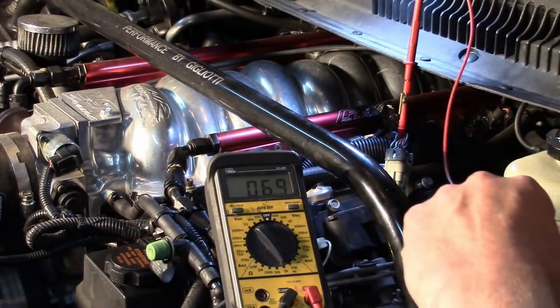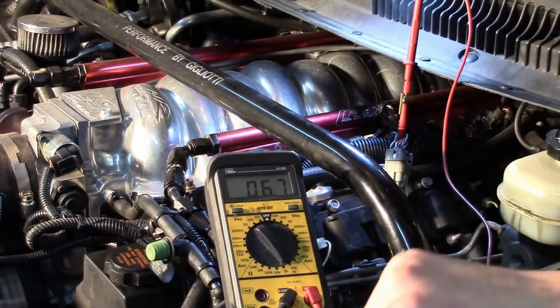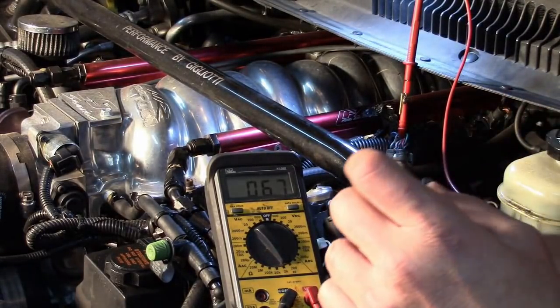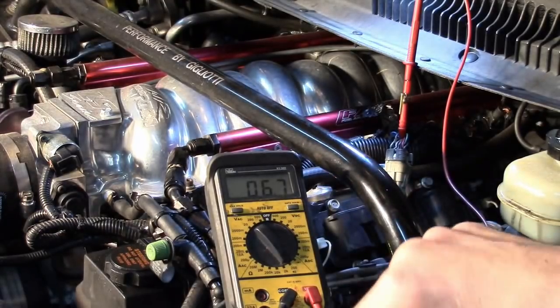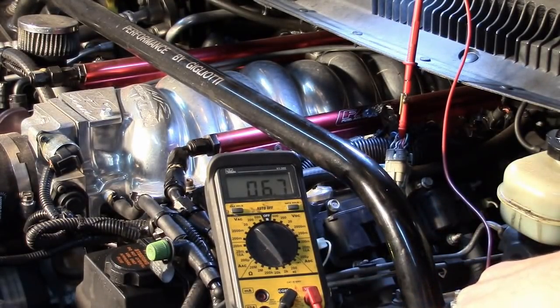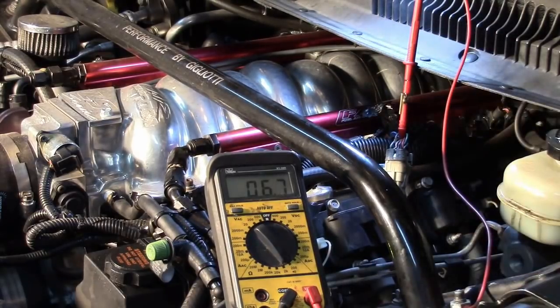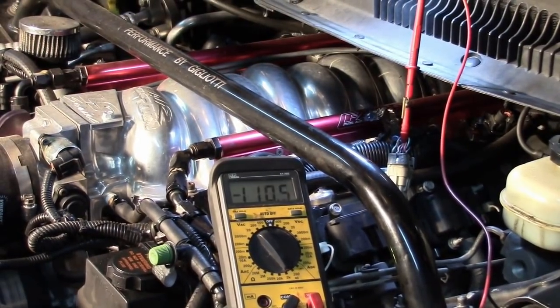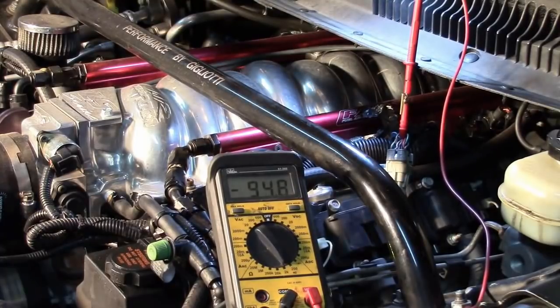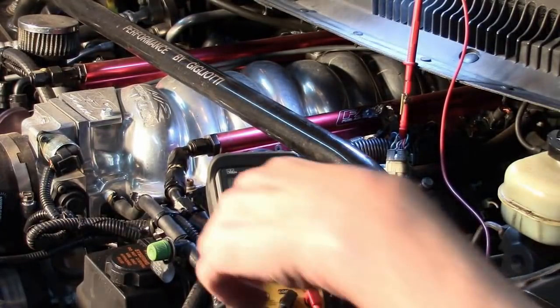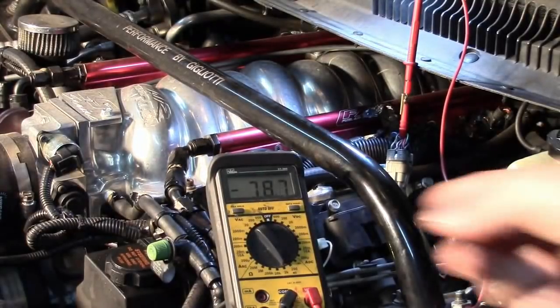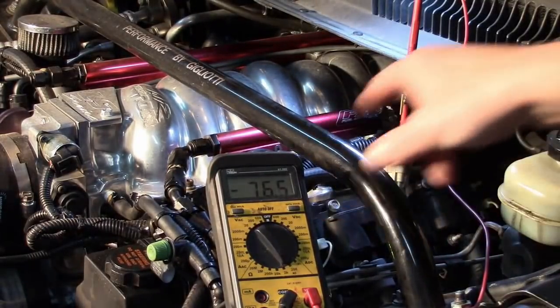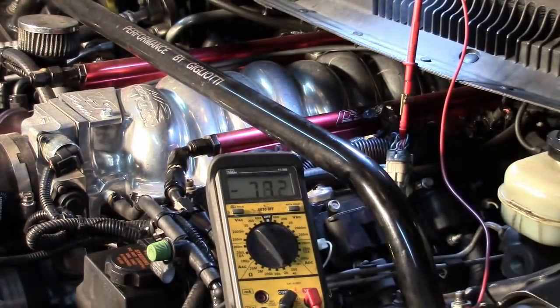there's my ground. That should stay constant ground running because, remember, we suspect it's grounded at the block. So if I was grounded through a switch circuit with the engine running, the ground would turn on and off. So I'm just going to start the car real quick and verify that we maintain our ground. Okay, you can see we're maintaining our ground. A little bit of noise on it with the engine running, but that is our constant ground, no doubt.